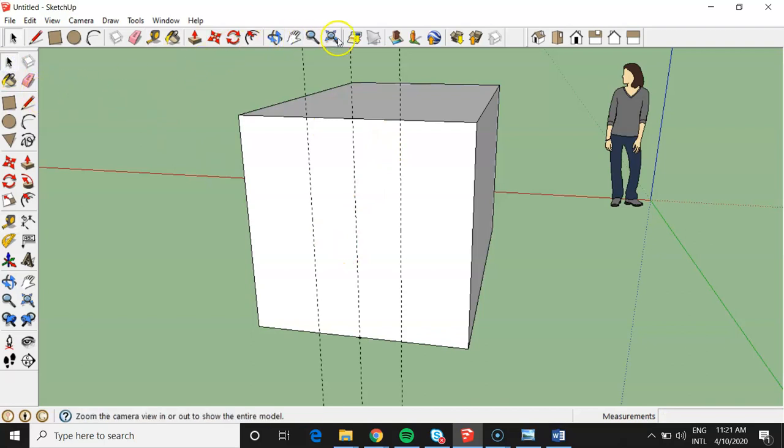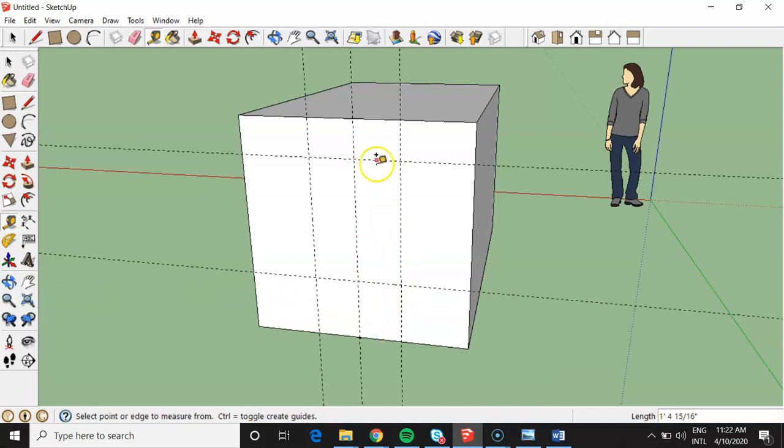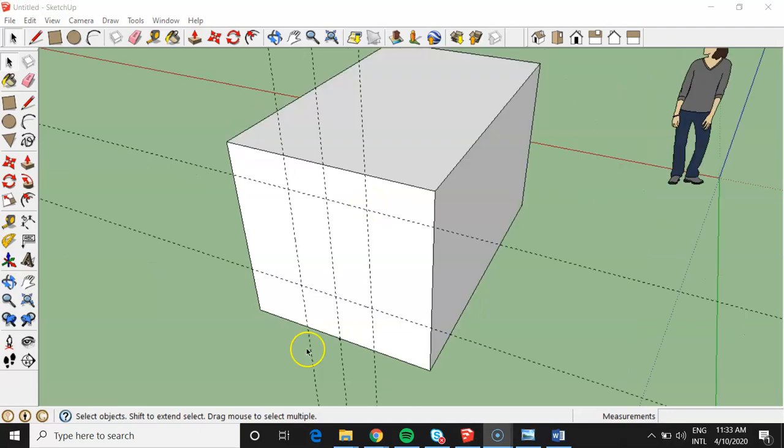Let's just stay with this thought and bring the head of the window. Let's say that is 10 inches off of the ceiling. This is only 6 feet tall, so I'm just going to bring something up and create it. This isn't a real room at 6 feet. Okay, so that's one way to rough in your window.